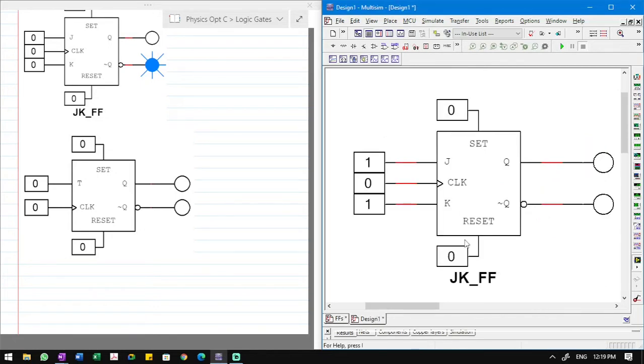Now I just want to talk about these two inputs here. Typically, if we are drawing a block diagram to answer a question, we wouldn't put these two controls above and below here, right? Now they have it as set and reset. Yes, it behaves like the set and reset we were talking about before, but this is really preset and clear, right? Now these above and below are independent of this input side of it here. This here is actually used, as I said, for preset and clear.